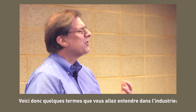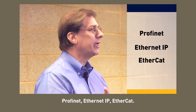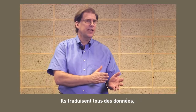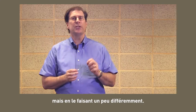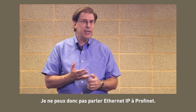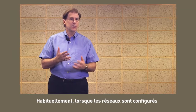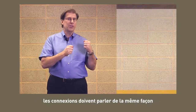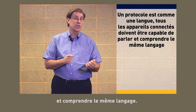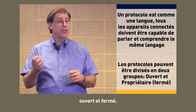These are some terms that you're going to hear out in the industry. Profinet, Ethernet IP, and EtherCAT. So think of them as German, Japanese, and French. You're all translating data, but you're all doing it a little bit differently. So I can't talk Ethernet IP to Profinet. I have to use a translator to do that. Usually the networks are set up so all connections must speak the same, and understand the same language. But the protocols now can be divided into 2 different groups, open and closed.